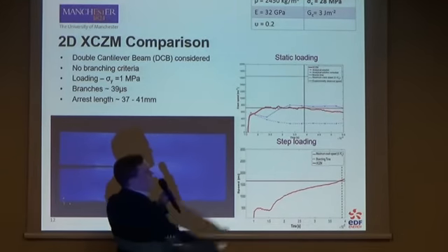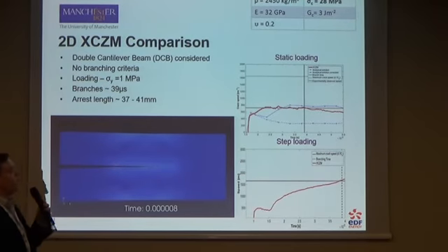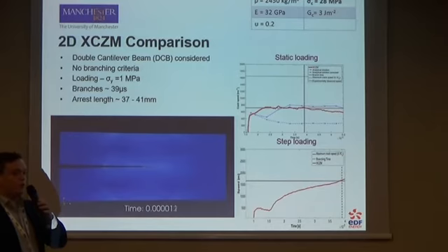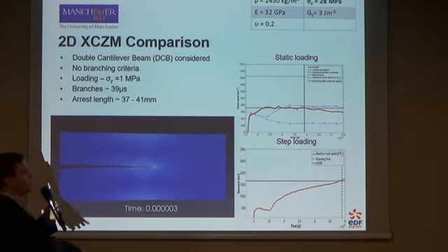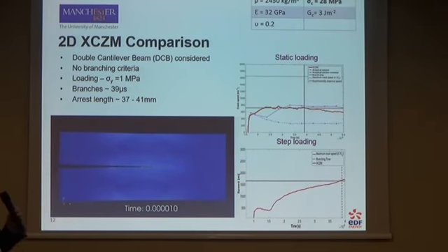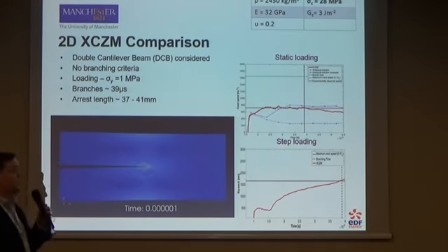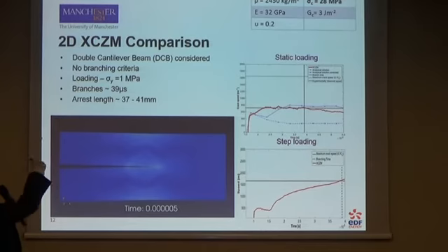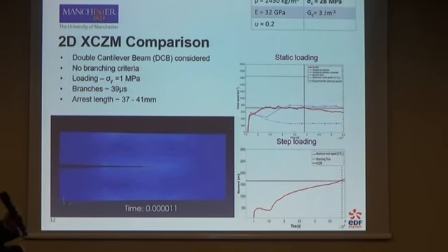The black line here, which is the experimentally observed crack speed in the experiment, is equivalent to the adjusted analytical speed, and also what we're observing was the explicit solver in XZ. Then under a small impulse loading, we also get to the point where we expect crack branching to possibly occur, which is about 0.7 of the CR, and that occurs at the time that it was observed for the branching to occur within the experiment. So we're in the right region of what we expect to see.